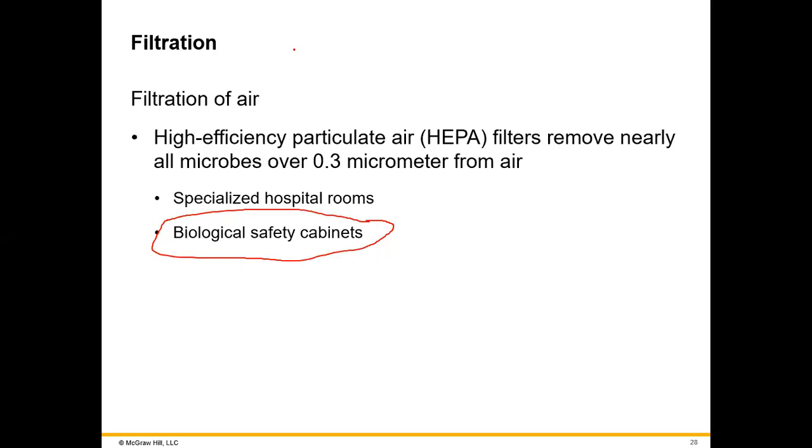The chemical hood has negative pressure inside. As I mentioned, the fan creates vacuum to suck the air out of the hood. So the air from the room will go into the hood and then get sucked up, along with any vapors of chemicals that are present in the hood. So this is a negative pressure.